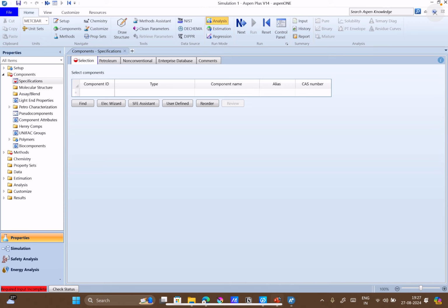So in this legend you can see the last point is shown as the azeotrope. So on the legend there is one square block and you can find that square block at the mole fraction of MIBK 0.35. You can see there is a square block, so that is an azeotrope point.